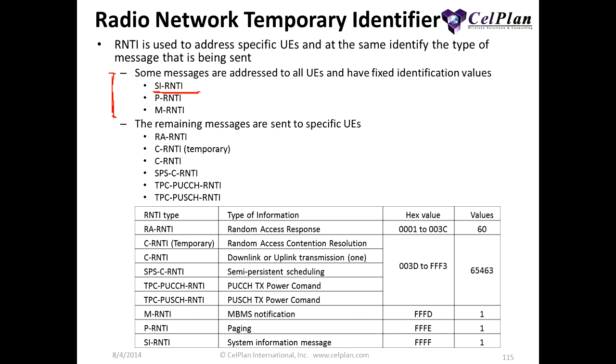So what the UE has to do is go into the CCEs, and in each CCE, go to where the CRC will be, and unscramble the CRC with its own identity or its broadcast identity, and then check the CRC. If the CRC matches, then the message was for John. Okay? But it has to do this with more than one identity.